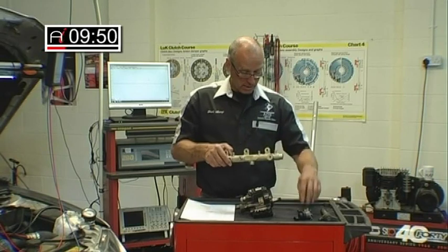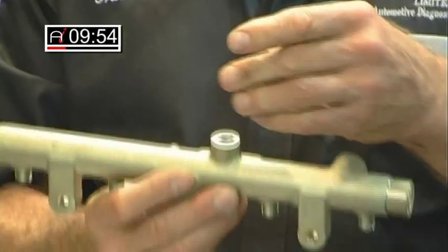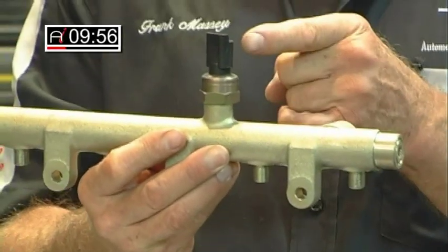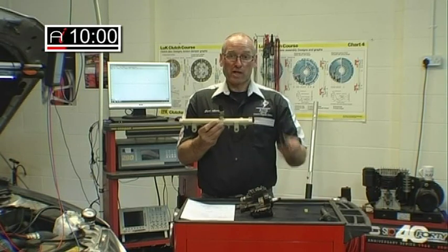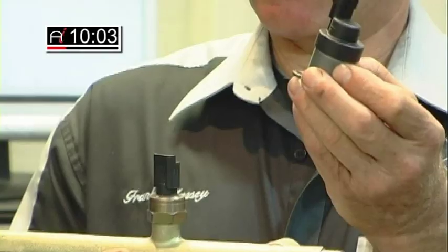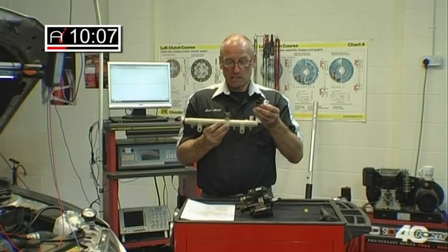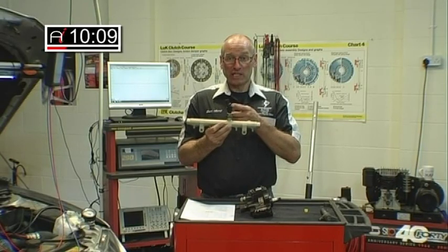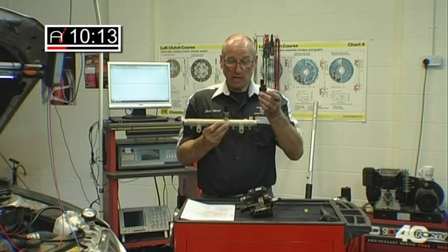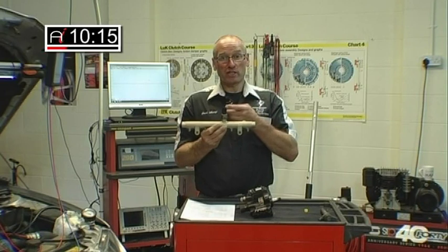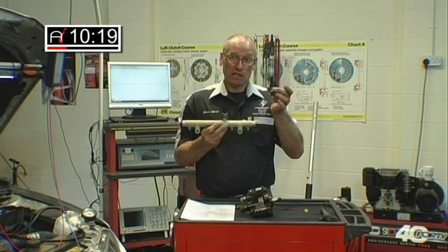The deviation that the diagnostic code refers to is a deviation in the output voltage from the rail pressure sensor with regard to the duty cycle of this valve. The two are monitored in closed loop very closely. So when a deviation in voltage is seen, it will compare the control duty. And what should happen is that the correct voltage should be achieved with the correct duty command to this valve. And we're going to monitor that.